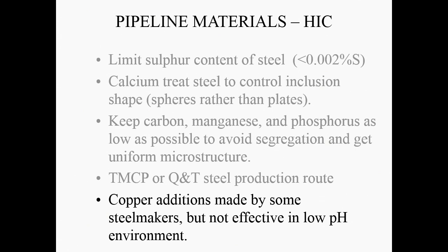Best example of that I can give you around here is the Angel of the North, which is made of a Corten copper-containing steel and is not painted, because the weathering of the steel creates an oxide layer which protects the steel from further corrosion.